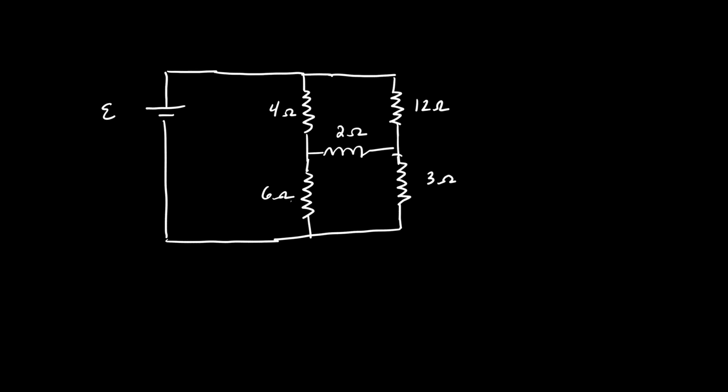Every loop generates its own set of voltage equations. And then, of course, you have V equals IR. So if you look at this particular circuit, it's challenging because you're probably going to generate a system of, I think, 6 to 8 equations that will then have to be reduced using the rules of systems of equations.